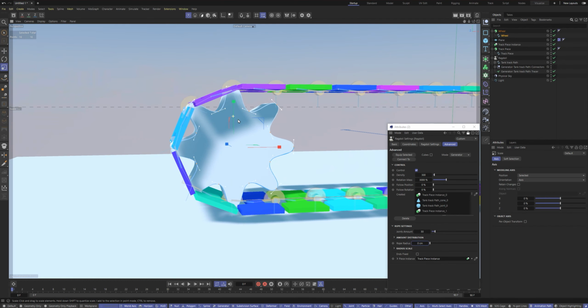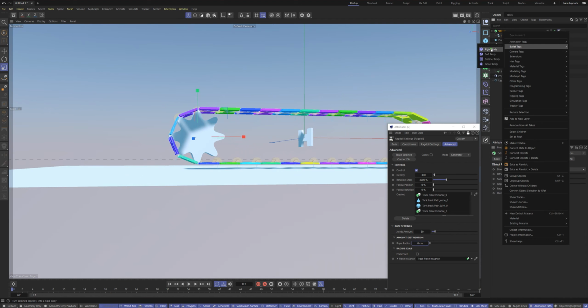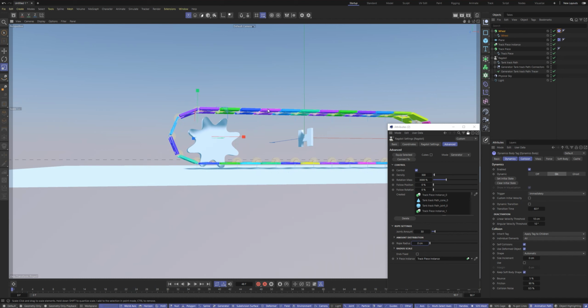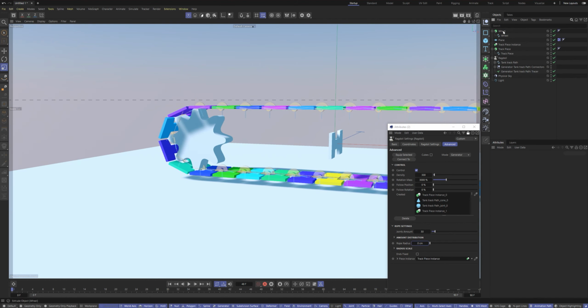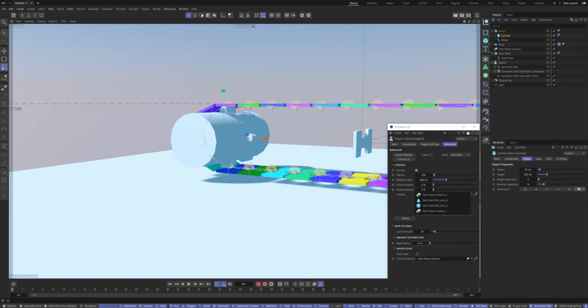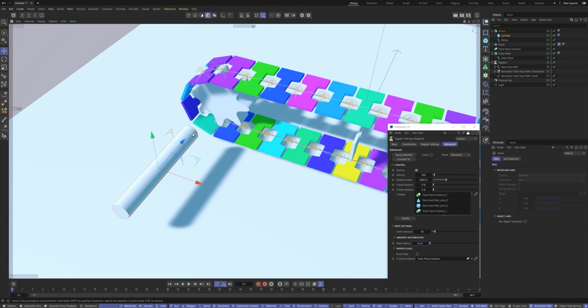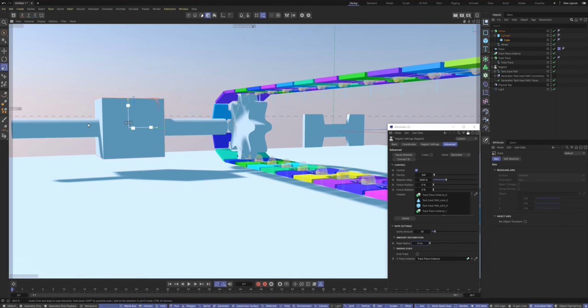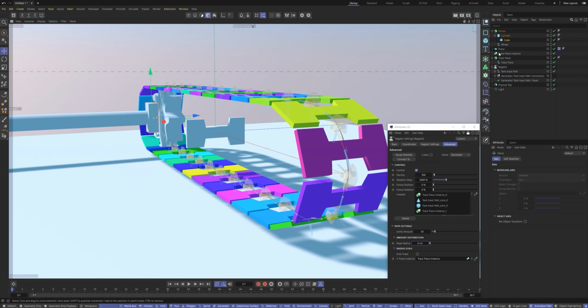The caterpillar particles must be correctly connected to each other. Two adjacent particles must only bend in the same plane. The gears and internal rollers will move up and down over potholes, but the rollers should only rotate in one plane along the track. Many different parts connected to each other require a lot of computations, steps per frame. This parameter especially affects the stretching of tracks. If the number of steps per frame is low, the track can stretch and jump off the gears.